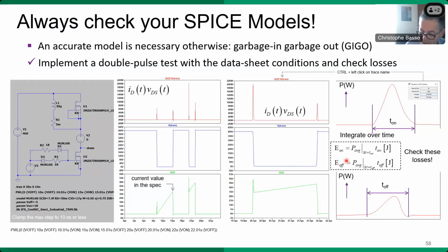Just one comment here. People very often consider SPICE simulation for switching losses assessments. It's a very tough exercise. I would say you can have a fairly good confidence when you determine average or RMS current using SPICE, okay? But when you do switching losses analysis, you normally have to include the power distribution network contribution. It means all the stray inductance and capacitance you have because of the PCB layout, because of the parasitics on this capacitor here that is going to decouple the high voltage rail.